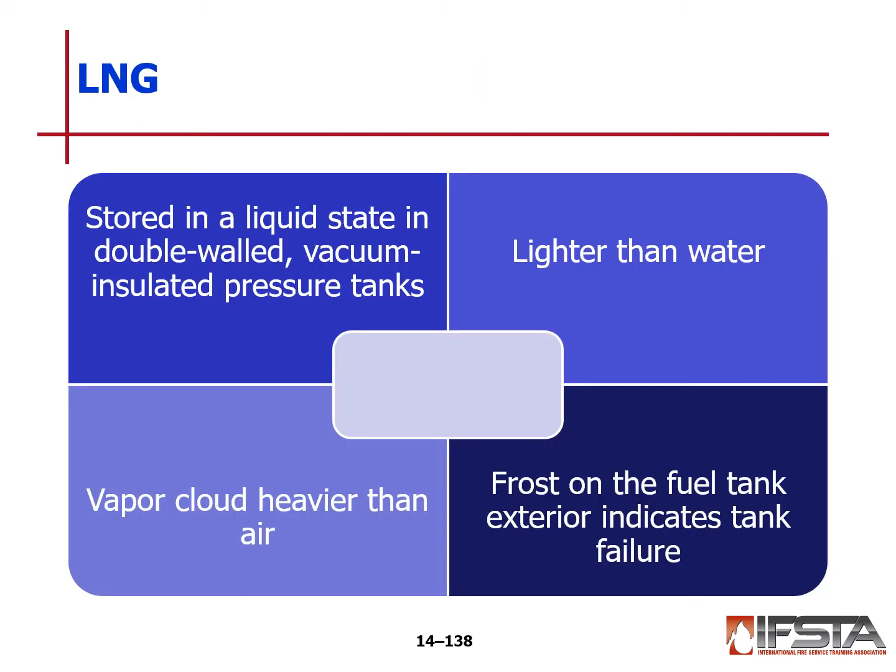LNG is stored in a liquid state in double-walled vacuum insulated pressure cylinders. It is lighter than water. The vapor cloud is heavier than air, so it will sink much like propane. Frost on the fuel tank exterior indicates the tank is leaking out rapidly and it will frost up.